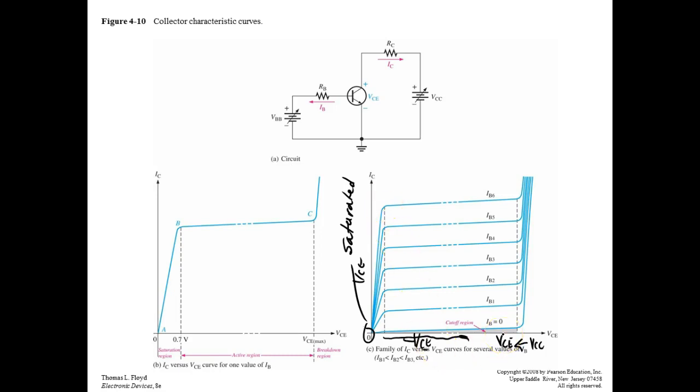If you measure VCC across here, then it's what? It's cut off. Now, if you keep increasing VCC, eventually you're going to hit a voltage we refer to as the breakover voltage. Is that good or is that bad? It's bad. The only time it's good is on a zener, and still, you've got to protect your zener, right?